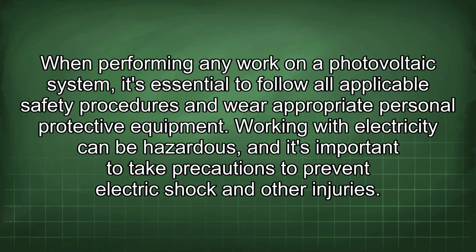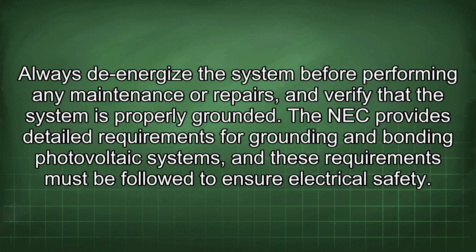When performing any work on a photovoltaic system, it's essential to follow all applicable safety procedures and, where appropriate, wear personal protective equipment. Working with electricity can be hazardous, and it's important to take precautions to prevent electric shock and other injuries. Always de-energize the system before performing any maintenance or repairs, and verify that the system is properly grounded. The NEC provides detailed requirements for grounding and bonding photovoltaic systems, and these requirements must be followed to ensure electrical safety.